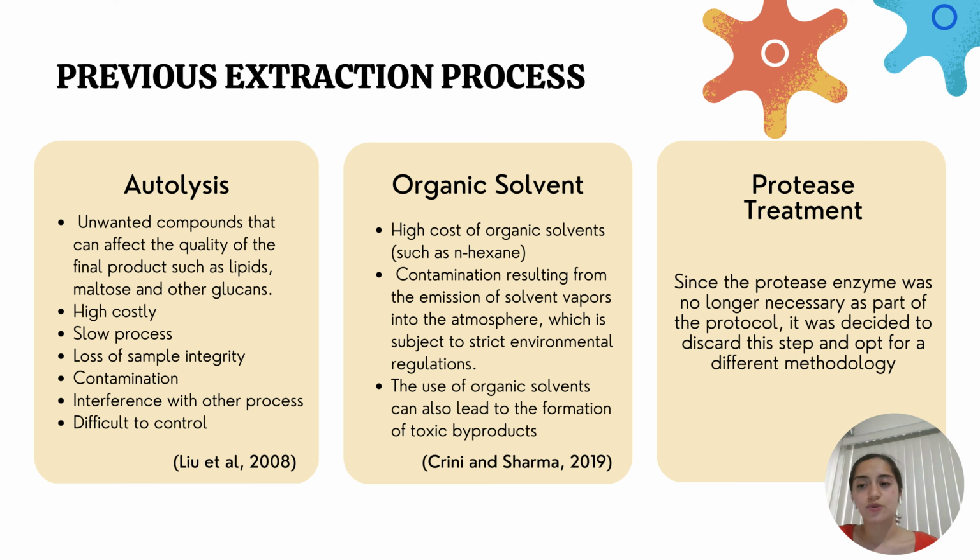And about the protease treatment, since it was no longer necessary as part of the protocol, it was decided to discard this step and adopt a different methodology. As I mentioned before, this new protocol uses high pressure homogenization as the lysis method and a one-step alkali extraction assisted by high pressure from a fermenter to optimize the time and the yield of the process.